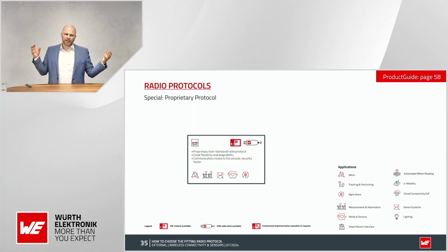So you can adjust the whole communication exactly to your application. Is it a one-press or one-button remote control? Then you have the need of a very small communication perhaps, or do you have a lot of sensor nodes, so you have high data rates, and you can adjust it very easily and very well to the application you have there. So this is the main advantage of the proprietary protocol also.